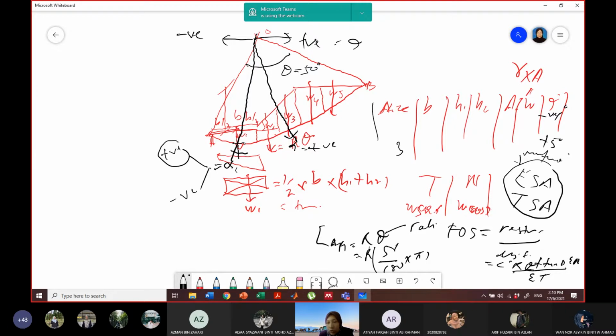I have seen that you are using the wrong formula to get the FOS for certain cases such as ESA or TSA. So please be careful when you read the question. Identify what kind of problem is given, what parameters are to be used in the analysis, and then how to start the calculations.